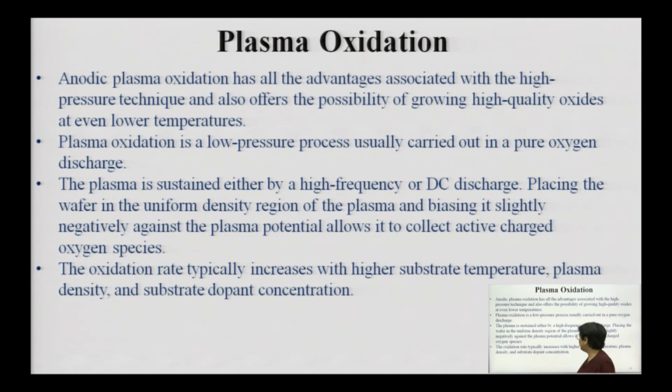Now, there is a tendency, whenever the temperature is elevated, for defects to penetrate further down the surface, and you do not want that to happen. Since you already know silicon is a brittle material, you need to handle it very cautiously, and you do not want any impurities to penetrate further inside the wafer substrate. For that reason, the wafer is not supposed to be heated during oxidation, so if you want the process carried out at lower temperatures, we can grow a high quality oxide layer using plasma.